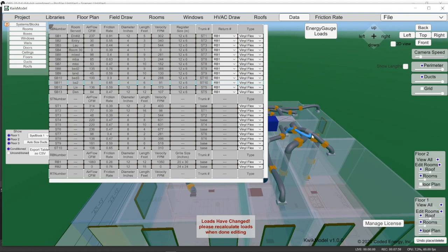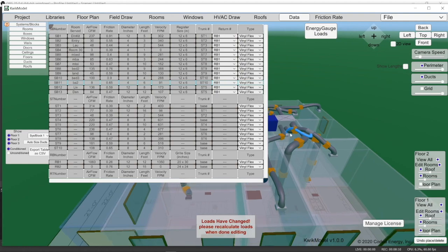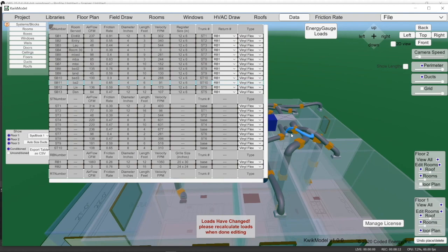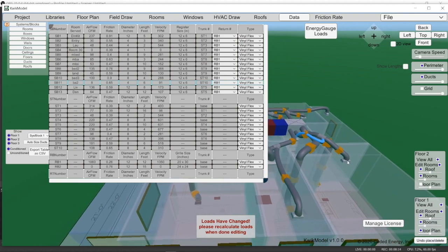I told you that's not going to need much air. 8 CFM. So even though that 4-inch duct is coming off doing a hard 180 and coming down, it only needs 8 CFM. It's essentially nothing. But it's going to get more than that, so we're good on that. I'm not worried at all about that one. Never was. What was I talking about? The other thing is the returns.